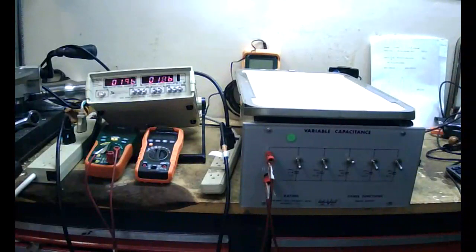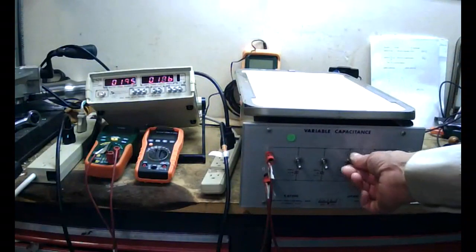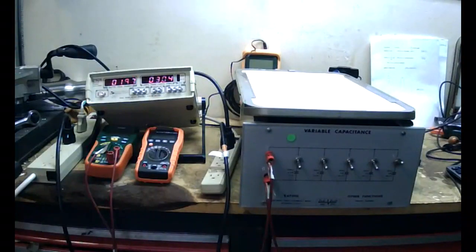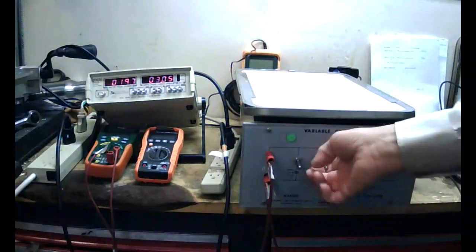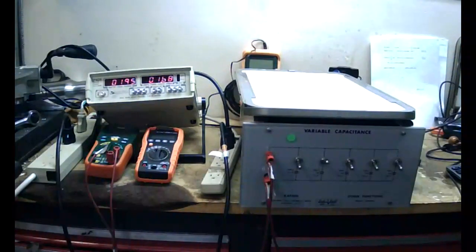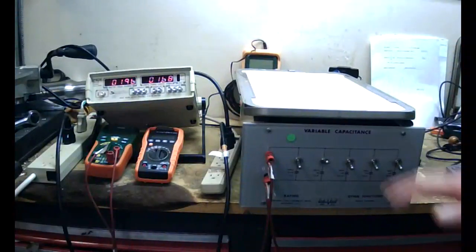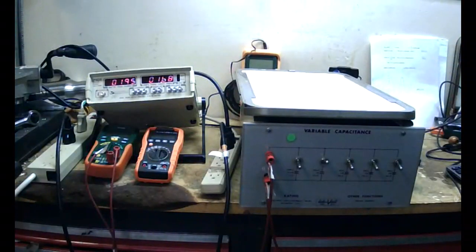So not quite as low as I got before. If I go to the 30, the current increases. At this point, I know that the power factor has gone leading, and we do not want leading power factor any more than we want lagging power factor because it increases the current. So this is the best I can do with the switch capacitors that I have.